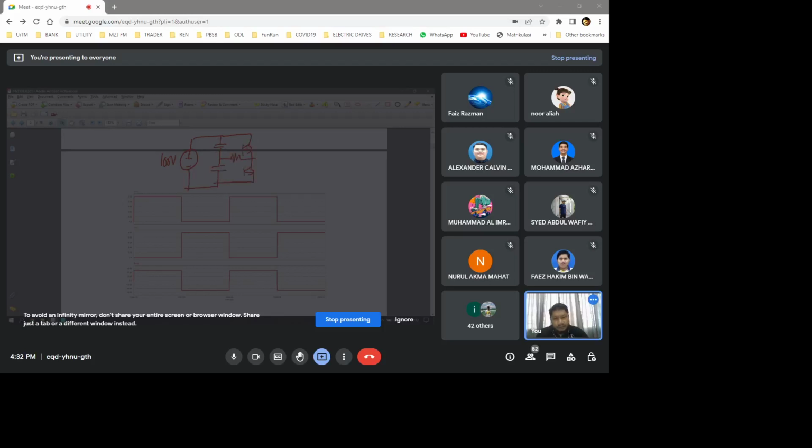Just focus on this input and capacitor here. We have 100 volt there, and therefore across that will be 50 volt, and there is another 50 volt. Because it's a capacitor, it will store 50 volt there, and the other one on the bottom side will be 50 volt. Plus minus, this will be plus minus.